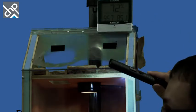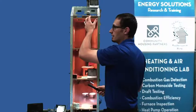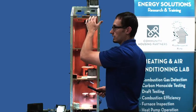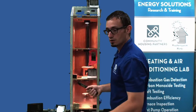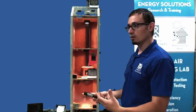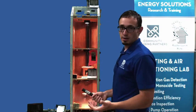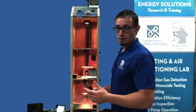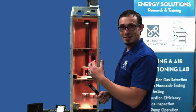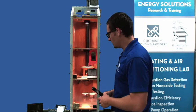So this is where you might think, well, yeah, I've got a roof leak. No, this is that warm, moist air rising into the attic, condensing on that roof deck surface and then dripping back down. So if you've ever had a roofing contractor try to sell you on a power vented attic fan to fix your moisture problem in your attic, your moisture problem is probably happening in the wintertime. And that's not even going to touch it. It only has the potential to steal your air-conditioned air out of your house and use electricity. So not going to be very beneficial.